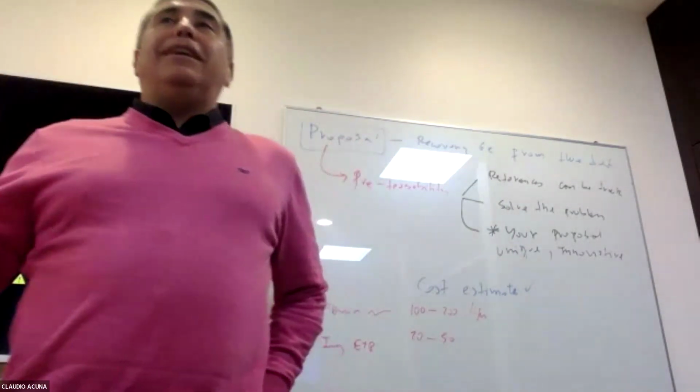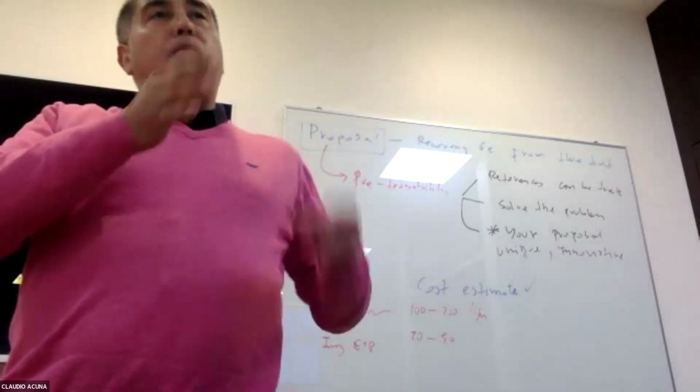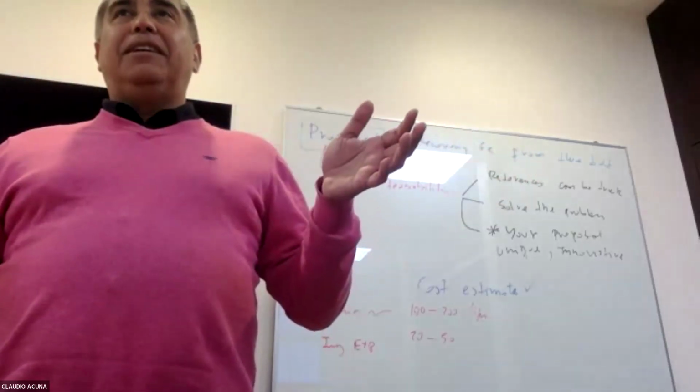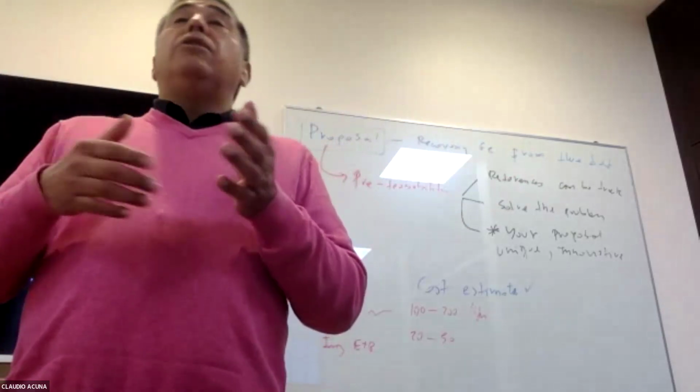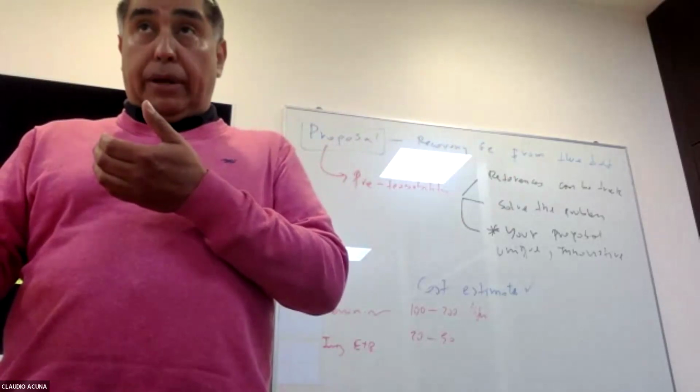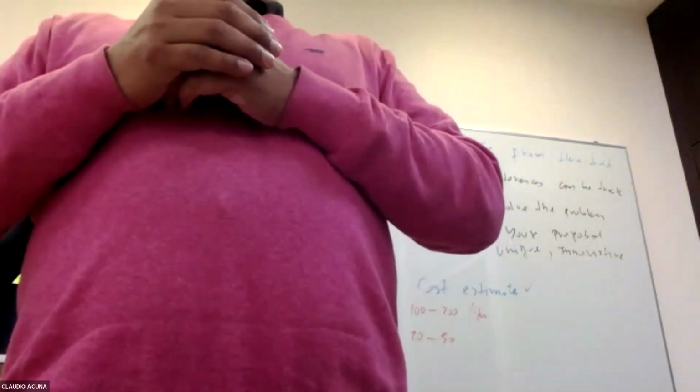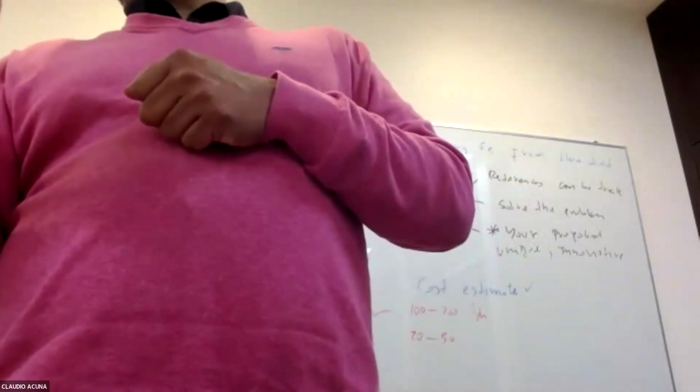Now you need to put in some efficiencies, and efficiency is very tricky. The more stages you have in your flowchart, the less you have 98% recovery, because you have too many stages. Best case scenario, even when you filter, you lose some material. So each stage adds an efficiency, and you multiply the efficiencies. So if you have 10 stages at 80% efficiency, you have very low conversion. Or 3 stages, you need to guess. 85, 95 is a very good process, probably leaching, but perhaps you require more time, so you end up with 60. Okay, to make a rough number, just an estimate, you can have 30% or 50% efficiency to be conservative.